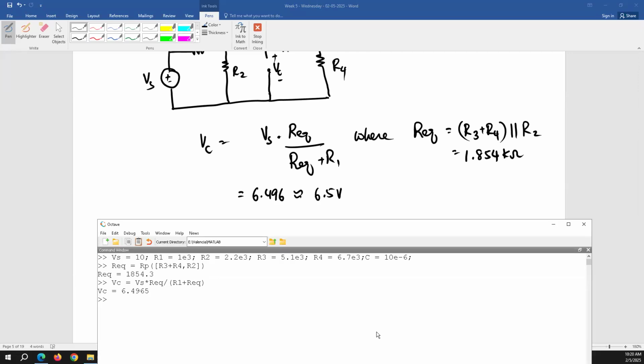Okay, any question, guys, about this? This is what I want you to do basically. Observe the circuit and don't jump into KCL, KVL. Observe the circuit and think how I can solve it the easiest way. And again, if you can apply Ohm's law, current division, voltage division to find whatever you're trying to find, you really don't need to write the equation of KCL or KVL or anything. So once again, observation is important. Take a couple of minutes, observe the circuit, and then decide what is the easiest path to find the value that you're looking for.